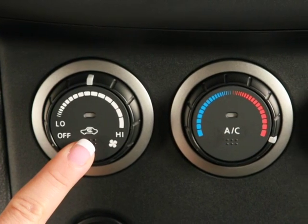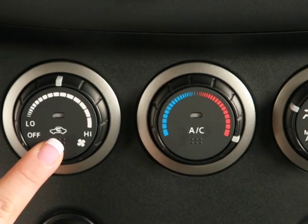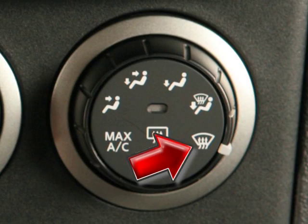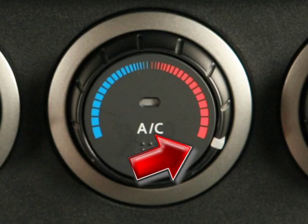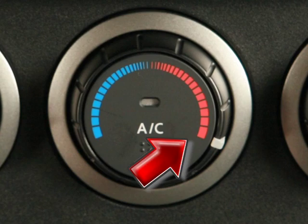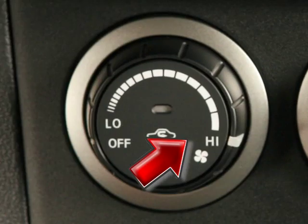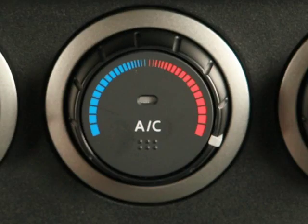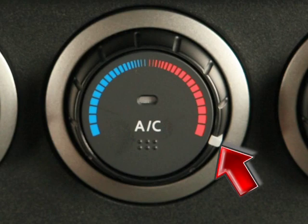To defrost or defog front and side windows, turn the airflow control dial to the defrost setting. Next, turn the temperature control dial left or right to set the desired temperature. To set the defroster on high, turn the fan speed dial all the way to the right. For windshield de-icing, your temperature selector should be turned to maximum heat.